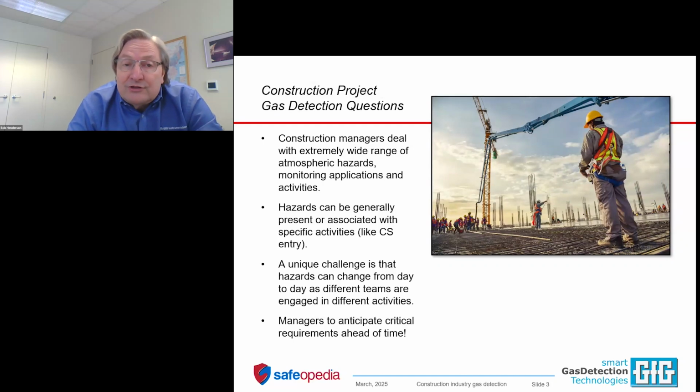Construction managers deal with an extremely wide range of atmospheric hazards, monitoring applications, and activities. The hazards can be generally present or associated with specific activities like confined space entry. A unique challenge in construction is that hazards can change from day to day as different teams are engaged in different activities. One day you might have an attic under construction because of the use of sealants or solvents. It becomes a dangerous permit required confined space.